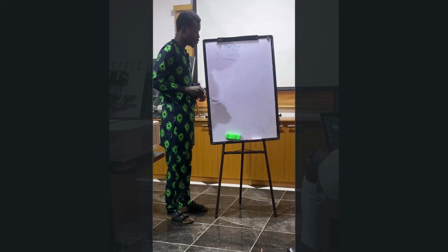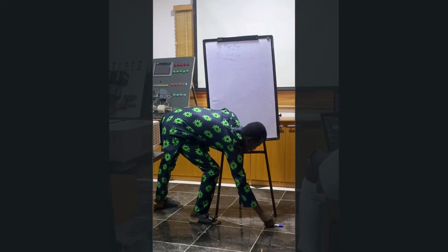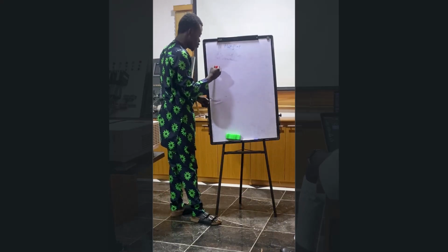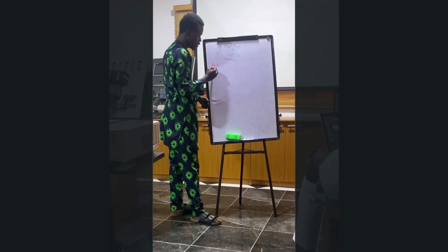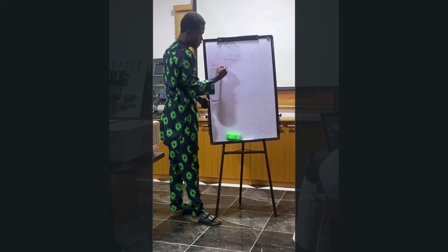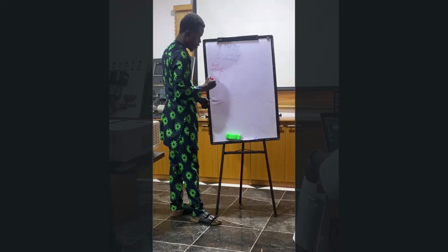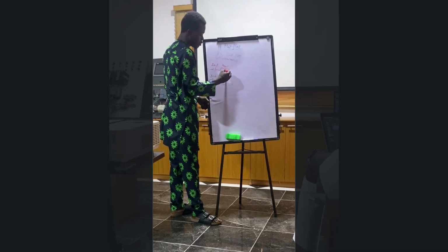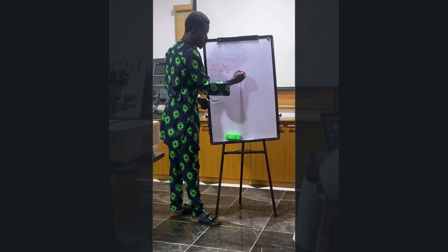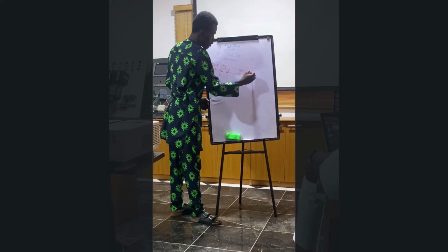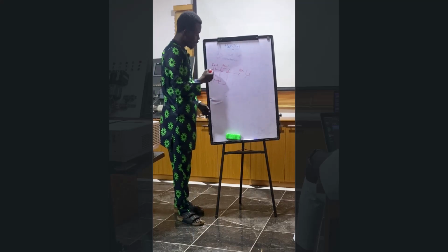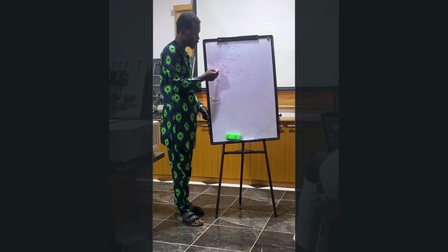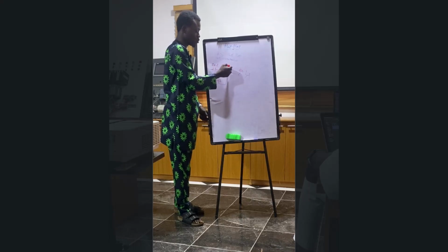So when you have your I0.1 serving as the reset, and your I0.0 serving as the set, say you have something like M0.1 here, EN, that's your output, Q2.1 for example. So when you press only I0.1, your signal state at this point will be what?